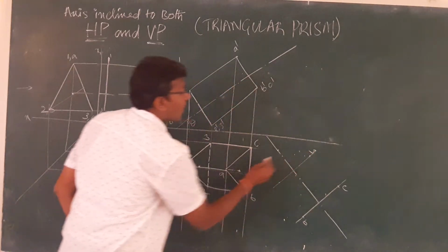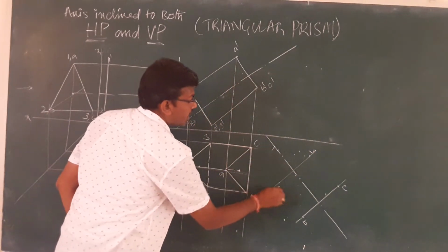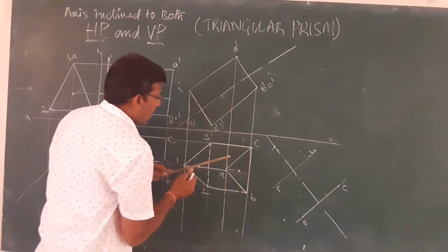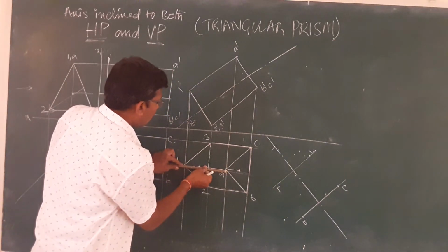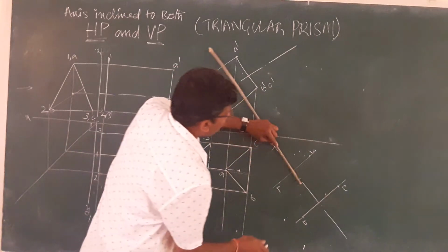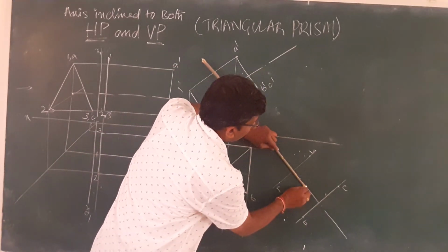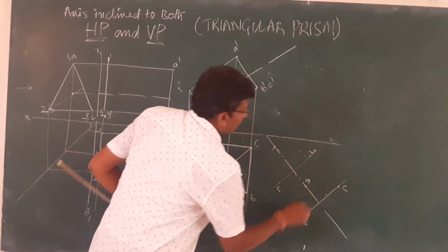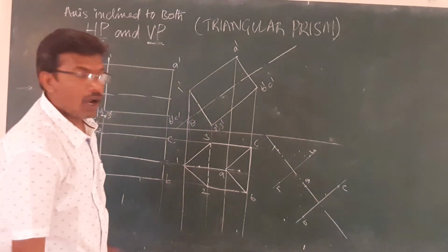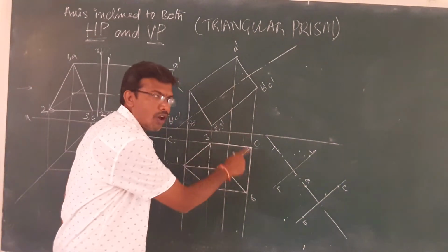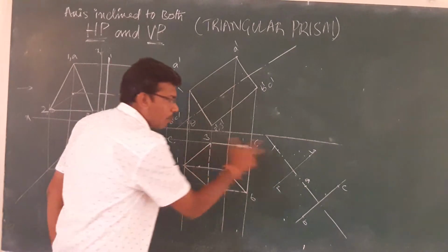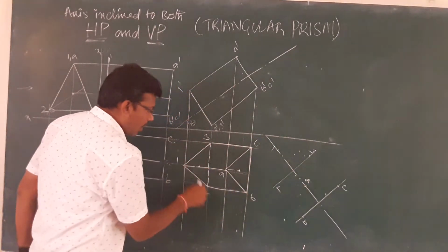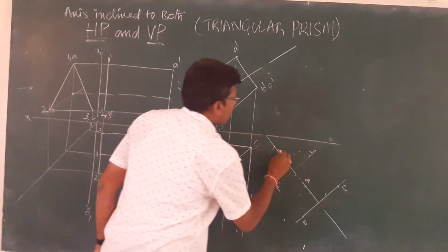And similarly, I will put the points here. This is third point, first point, this is second point. Okay, and I note the length of 1 to A, and I will put the 1 to A length. So this is A. After taking the lengths from the normal scale and putting them on this one, simply I draw the same diagram here.